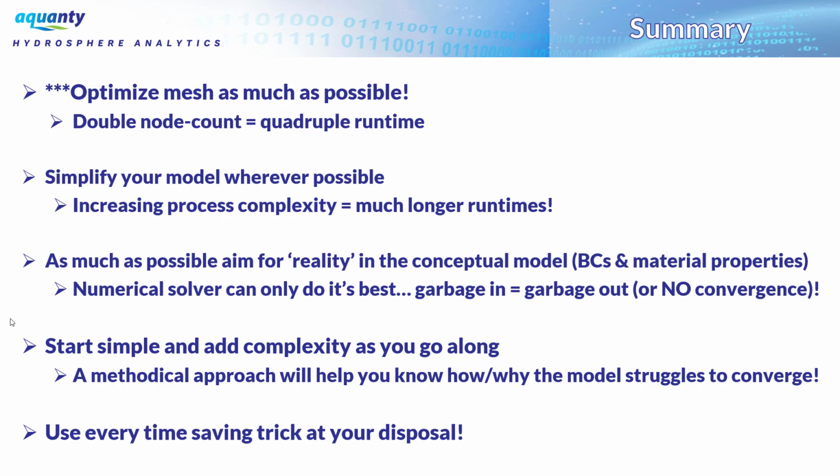And again, this can really help in a staged approach. Don't go straight for a density-dependent flow model. Run your flow simulations first. Those will be a lot faster than the subsequent solute transport simulations. And start simple and then add that complexity as you go along.